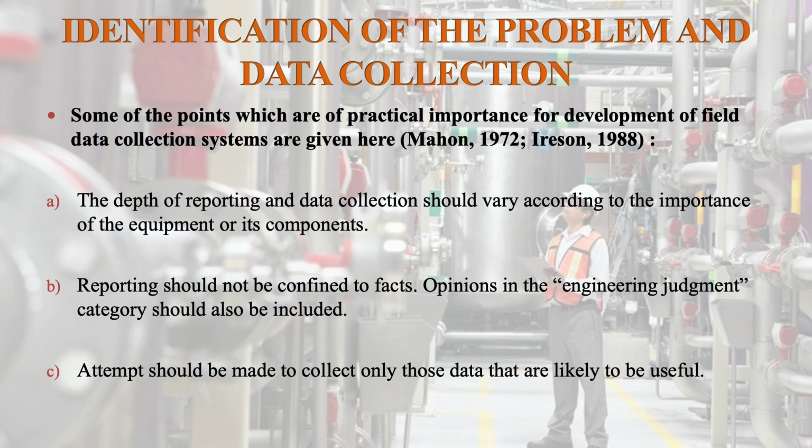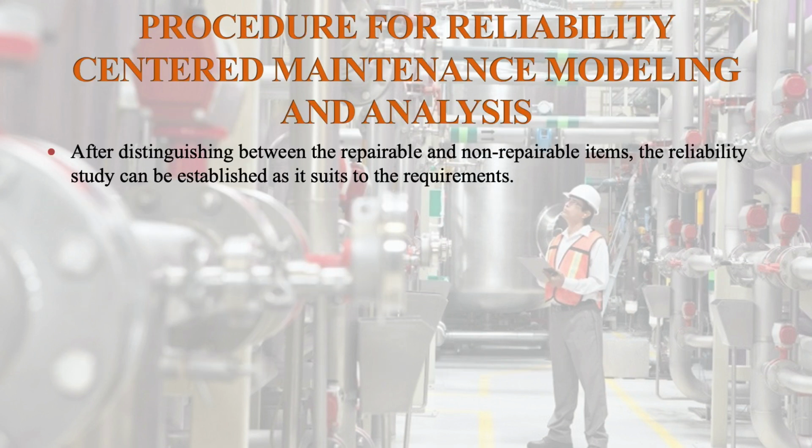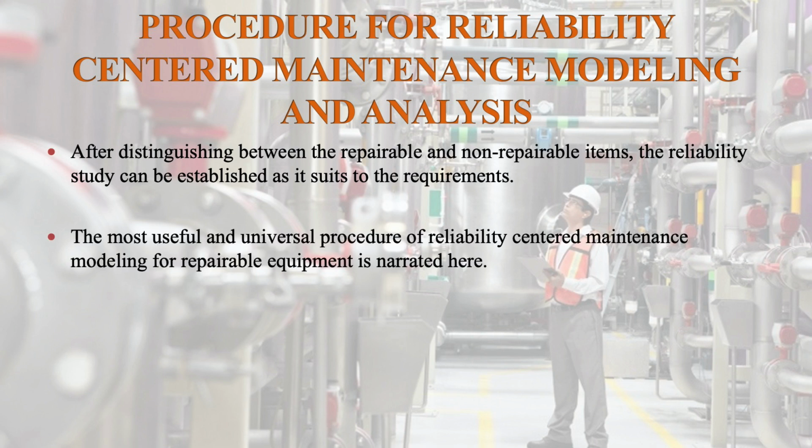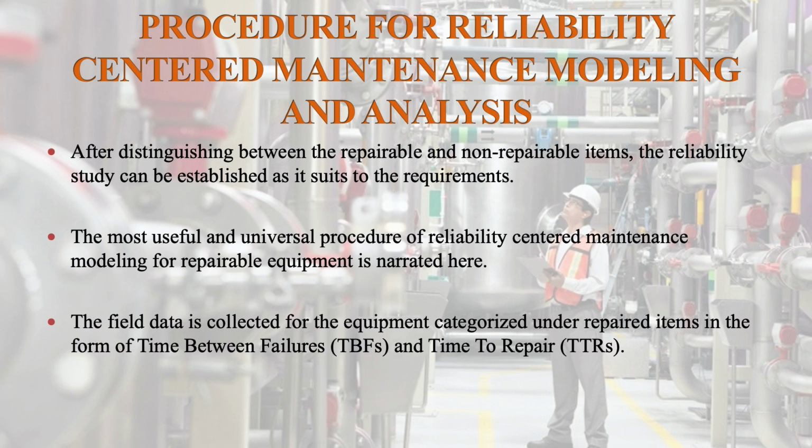Procedure for reliability centered maintenance modeling and analysis. After distinguishing between the repairable and non-repairable items, the reliability study can be established as it suits the requirements. The most useful and universal procedure of reliability centered maintenance modeling for repairable equipment is narrated here. The field data is collected for the equipment categorized under repairable items in the form of time between failures and time to repair.